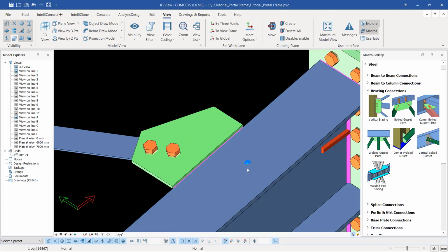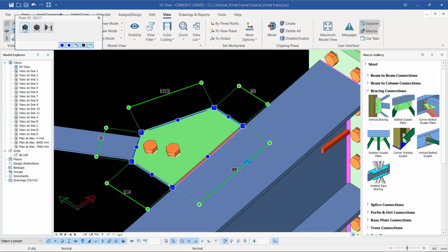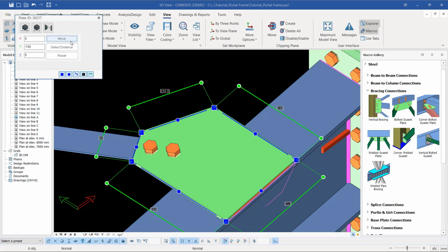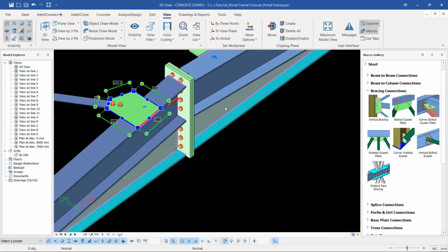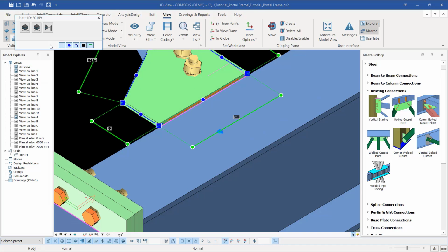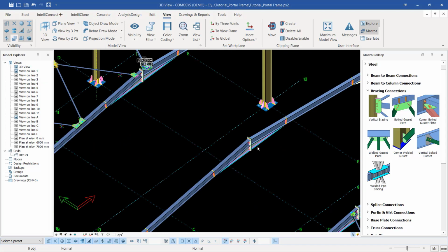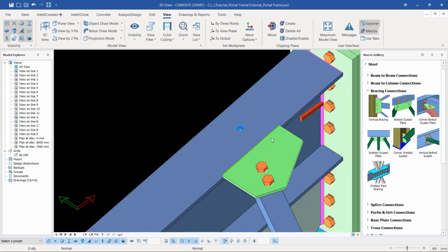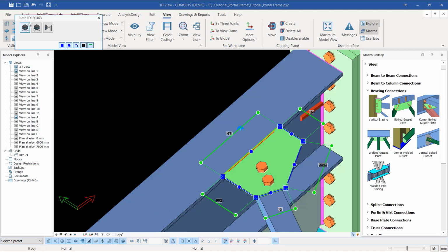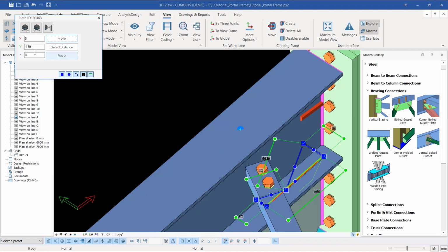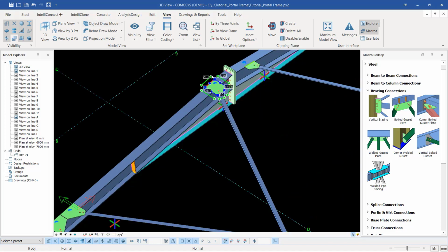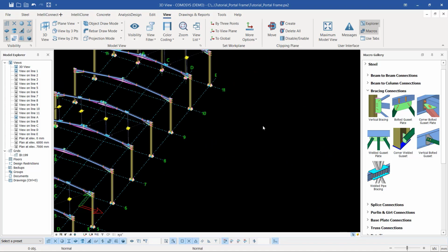Now, if I bring this close, you can actually notice that this hasn't adapted to the adjustment that it was copied along with. So I'll select on that member, pick on that, and try and adjust this. If you click adjust, it will just respond. I'll select on that, pick on that and adjust that, it will respond, and we'll modify that bit by bit. I'll do the same thing here and select on that and pick on adjustment and select that. If that's not responding, make sure you remove the prefix negative and click OK and do the same thing there. So that's how you can brace.